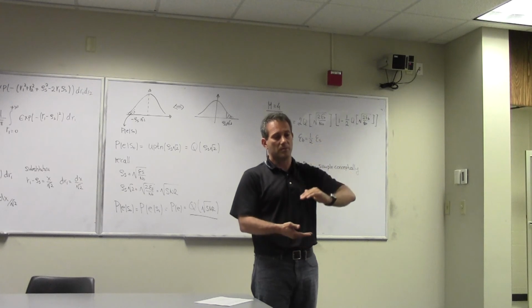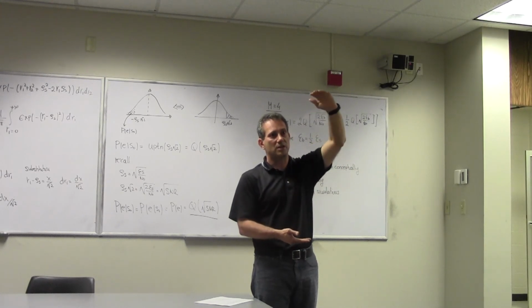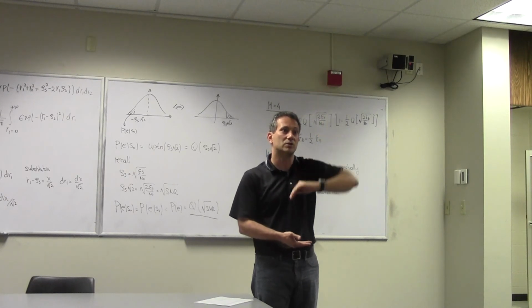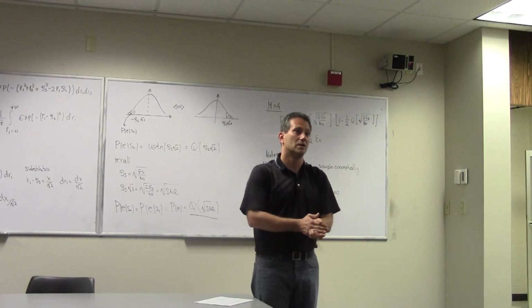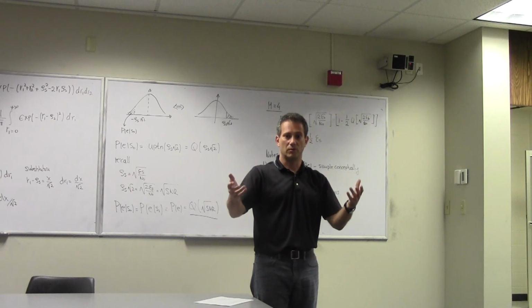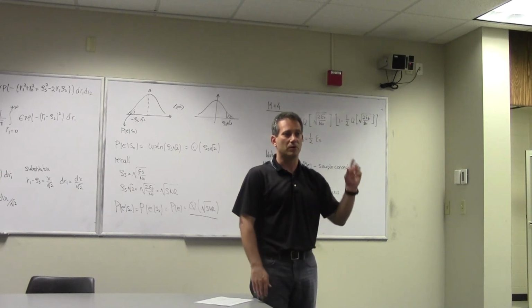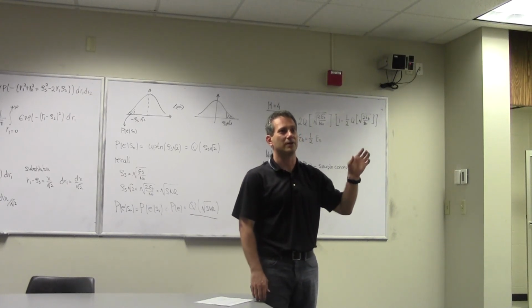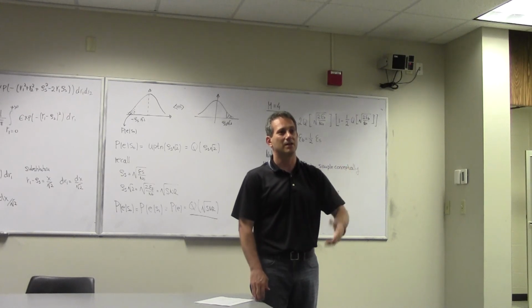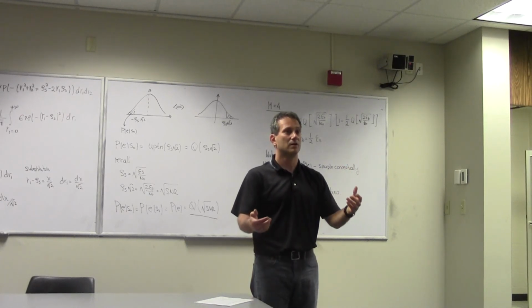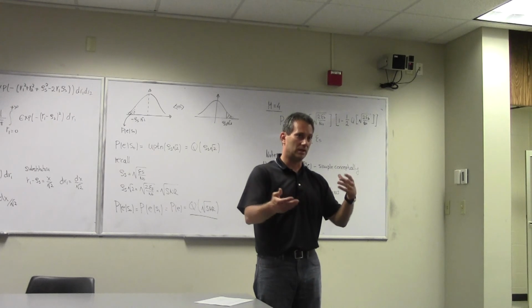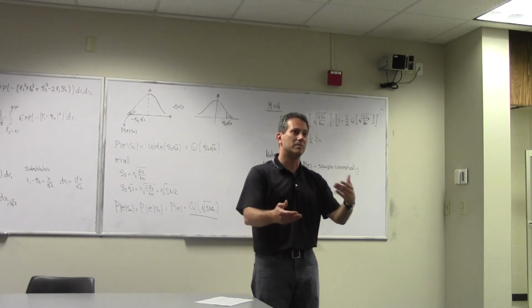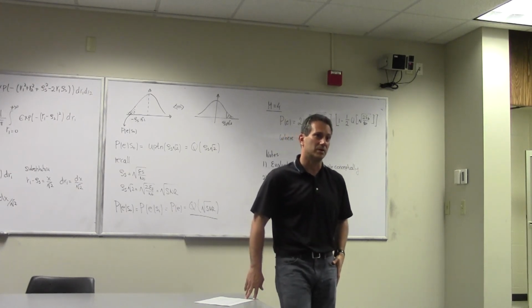Or go from QPSK to 16QAM, give him another boost in throughput, and then go all the way to 64QAM in some cases. We all know that if you want to have good throughput, you need to have a lot of bars, right? That's exactly it, because systems are getting smarter, so they have adaptability based on the signal-to-noise ratio that they experience.